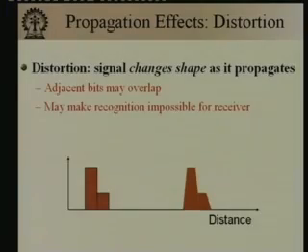So, finally, the relative strengths of these different frequencies will be different when you go to the far end, that means when you go to the receiving end, and when you add all this up, you will get a different shape. You will not get your old square shape or whatever shape you had sent. So, this is called distortion.